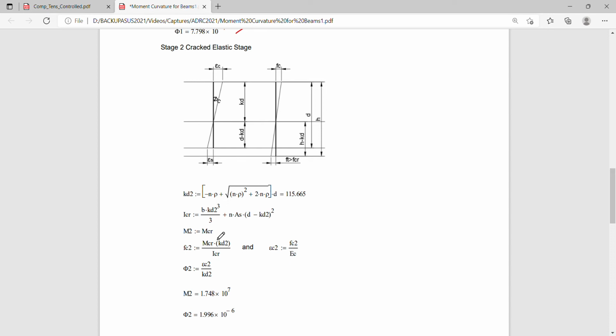So this is now two boundaries, two sets of cracking moment in one instant, because at the snap of a finger, let's say, the beam now transforms from an uncracked beam to a cracked beam. So there's a sudden jerk in the resistance of the beam for the moment.